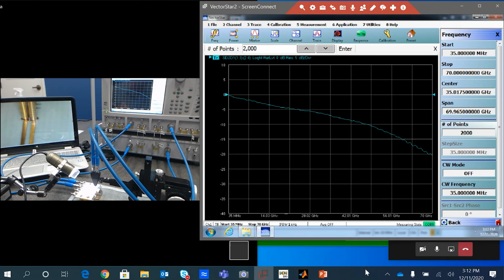And in order to verify they are or not, we have a camera here that's showing the probe tips. It expands it on the display, as you can see here on the PC. So those are the two signal pins within the probe itself. As you can see, there is no ground. So we have no common mode path, just a differential path with crosstalk. And they're making contact with the differential line, as you can see on the trace.